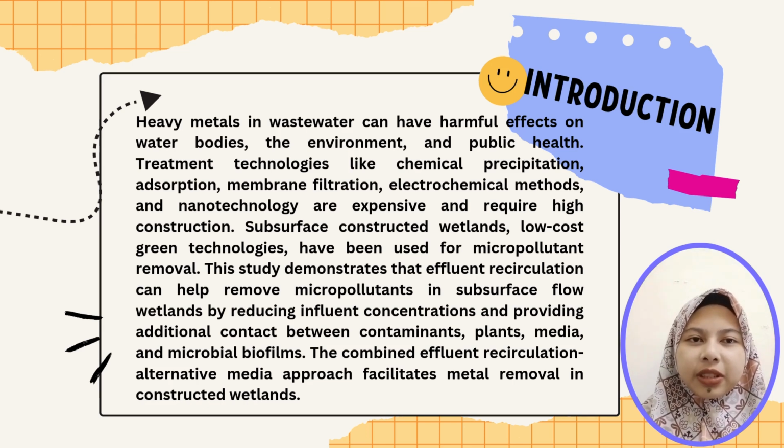This study demonstrated that influent recirculation can help remove micropollutants in subsurface flow wetlands by reducing influent concentration and providing additional contact between contaminants, plant media, and microbial biofilm. The combined influent recirculation and alternative media approach facilitates metal removal in constructed wetlands.